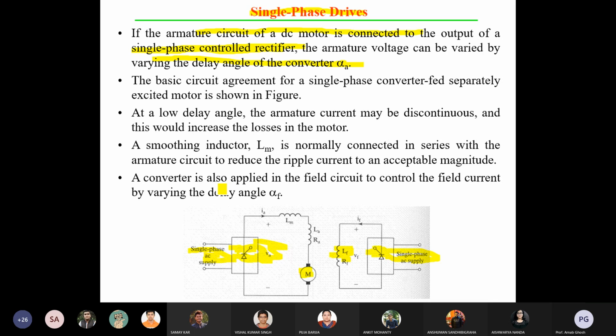Triggering methods such as RC triggering and UJT triggering you have already gone through in your power electronics course. Still, some aspects of triggering the SCR are quite different compared to the MOSFET. Normally, if you want to trigger the SCR, first you have to use a zero crossing detector, ZCD. I think you know the configuration of the ZCD.